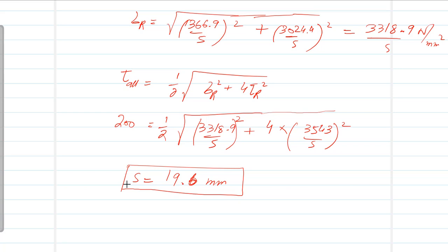And last but not the least, if the same problem comes with a plate, this is for the beam. Also, I've given you a very difficult case in which the weld is unsymmetric and it is a beam. So for an unsymmetric weld, we have torsional shear, bending shear, bending stress, and direct shear.